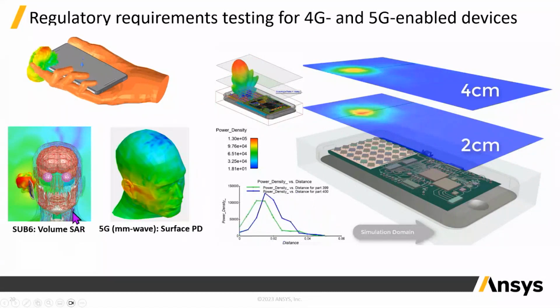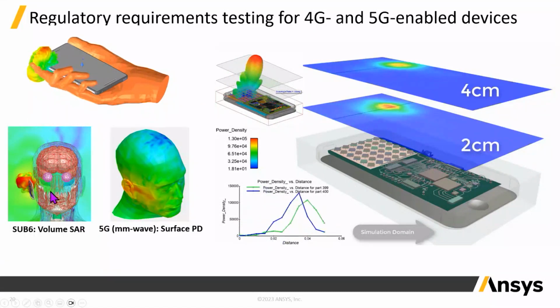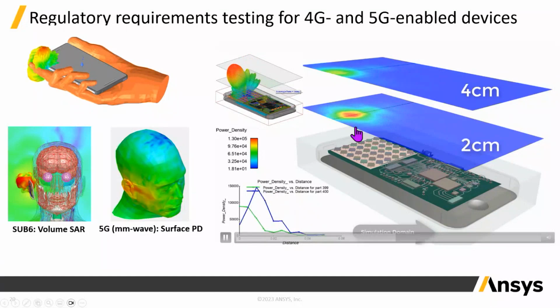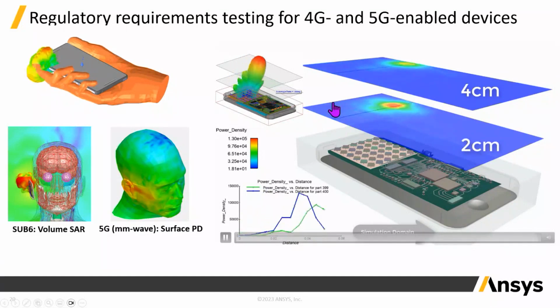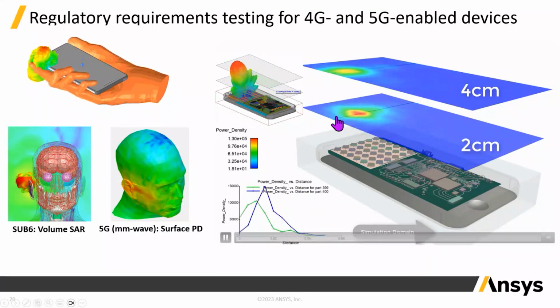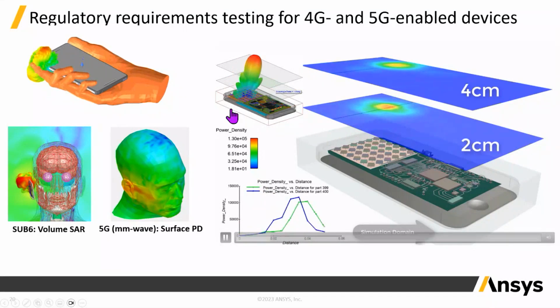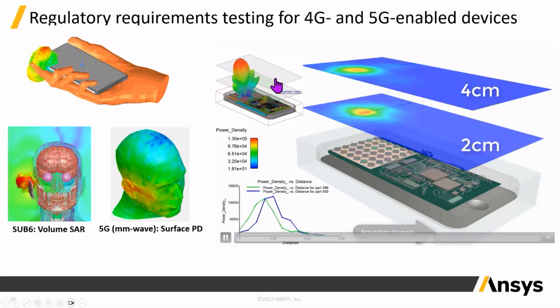So if you have a device, you can run this SAR simulation. It will predict how much the SAR is, and it can also do the power density calculation based on the FCC regulations, and it will tell you what the worst case of SAR is based on beamforming and other things.